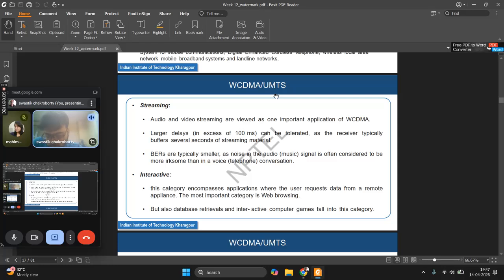If you want good quality video, you have to settle for a higher transmission delay. So even at 240p there used to be buffering, which is unimaginable now, but back then even that was normal because we could not achieve the transmission delay with the BER needed for unbuffered transmission of video.